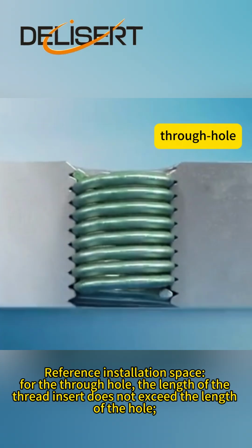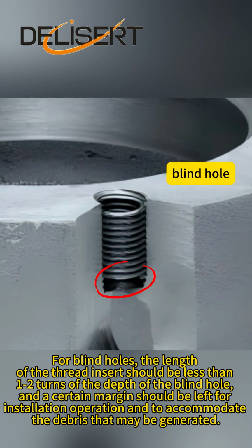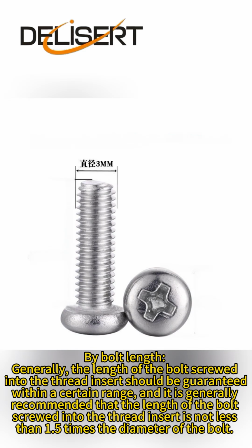Reference installation space. For the through hole, the length of the thread insert does not exceed the length of the hole. For blind holes, the length of the thread insert should be less than the depth of the blind hole by 1 or 2 turns, and a certain margin should be left for installation operation and to accommodate the debris that may be generated.